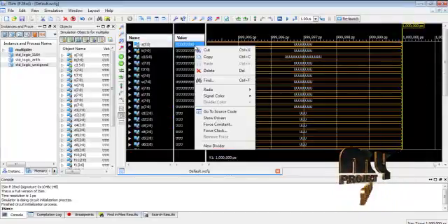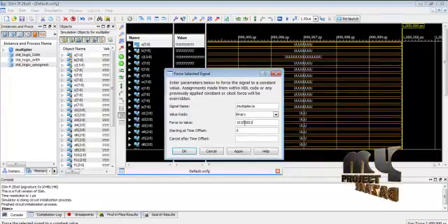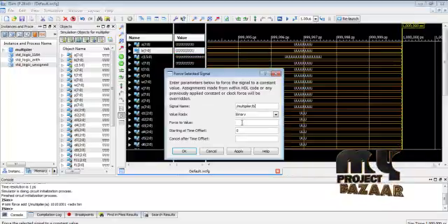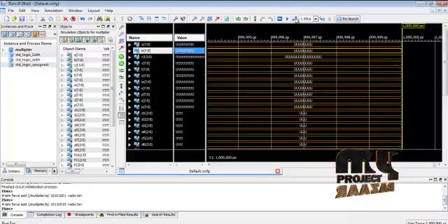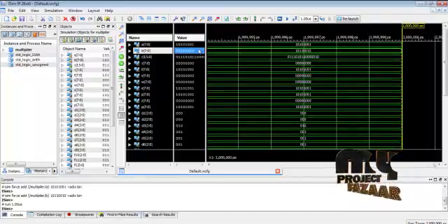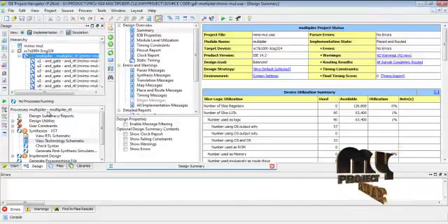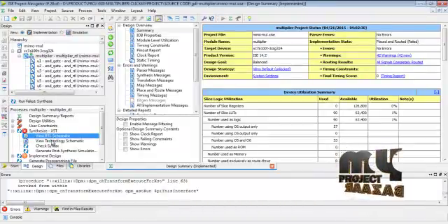Then we apply the input in binary in our architecture. Any binary input is applied to A and B, the multiplier and multiplicand. Then we run for the time specified on the toolbar, and we get the output result for the multiplier architecture. Then we close the simulation and select the implementation process, which describes the RTL and technology schematic.